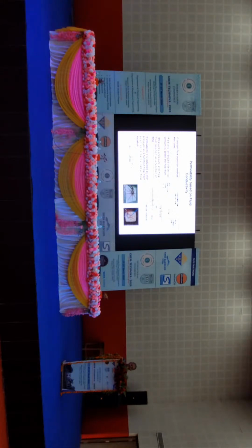So I have pressure data, and the flow front data like time of reach as well as distance of reach. With these three data and Darcy's equation, I can get the permeability data. The equation is P inlet equals Q mu by 2 pi t phi K times ln of R by R naught. From this, the only unknown is K. Phi is the porosity value, which is obtained from the areal density of the mat.